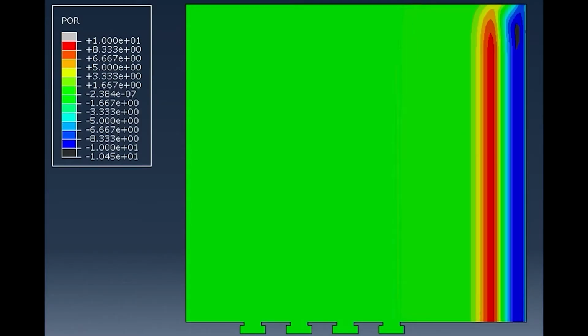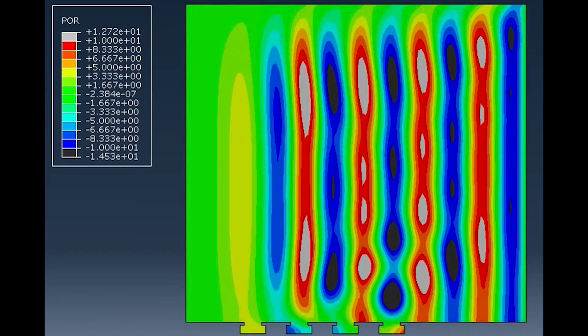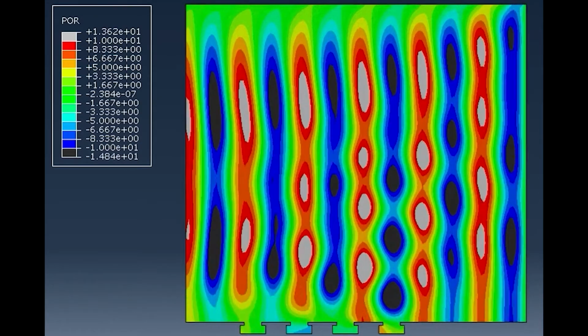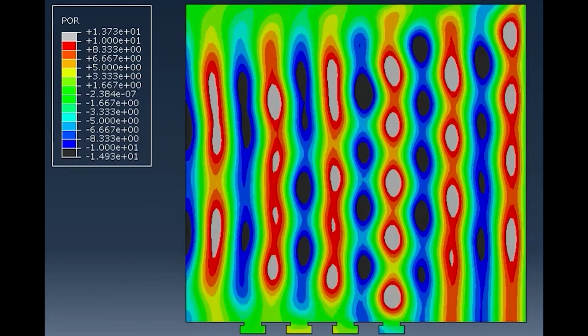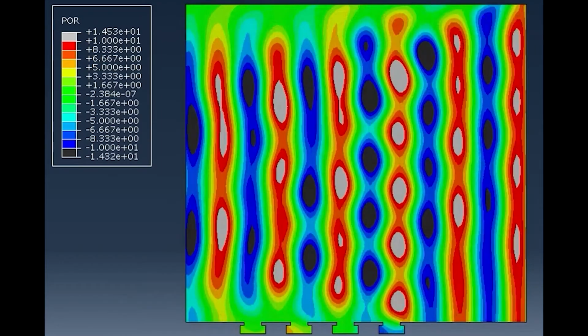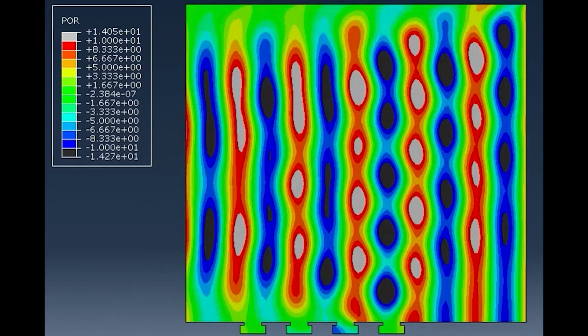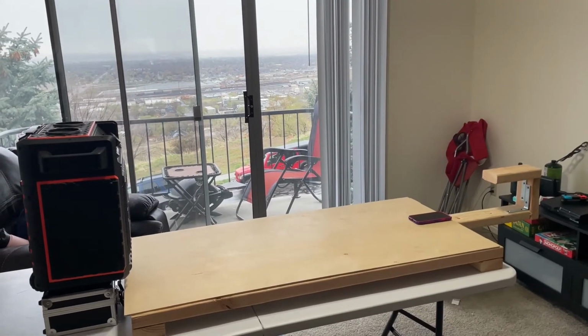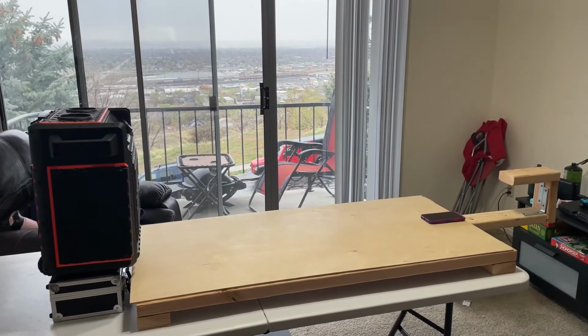This clip is the contour plot created in our Abaqus analysis with acoustic pressure waves traveling across the resonator plane. The acoustic pressure load we added to the system is a line source rather than a point source, with the bottom plane as a solid boundary and the top plane and side planes both simulated as an open air environment to create simulated infinite space. In our analysis, 3D modeling was unnecessary as it would add a lot of variables that are not needed for sound modeling. Since you've already seen the theoretical part of our project, I'd like to show you the experimental part.